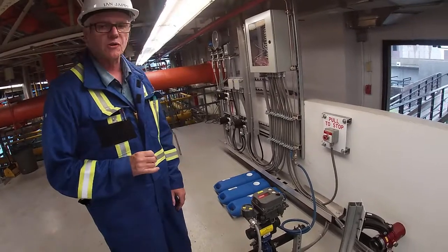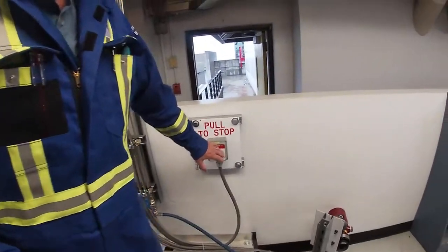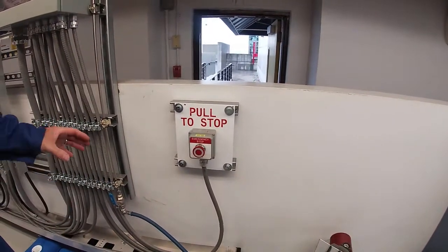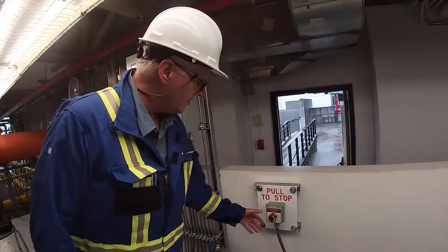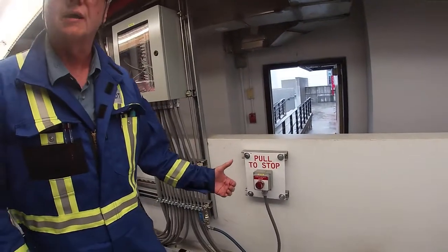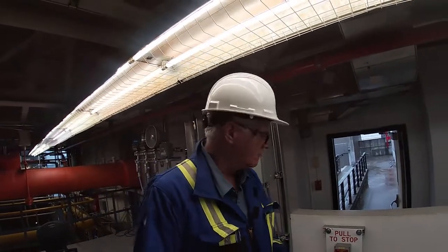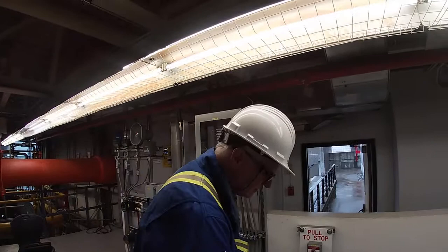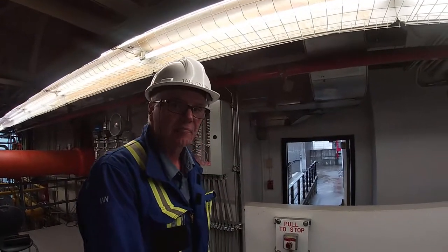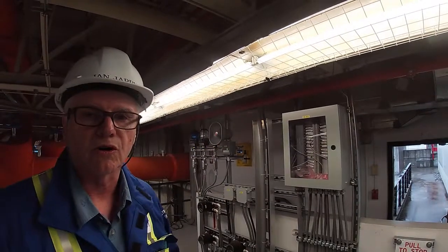And the last piece of equipment that we have here is an emergency stop. If you go around and look in your plant, you'll probably notice you have some pull stations. They're all different types. This one says pull to stop, the reason being that if I lean up against it, I wouldn't hit the stop button and shut everything down. When we test this, it will close the valve, shut down the pump motor, and it will also enunciate the horn, and all the strobes will go off.